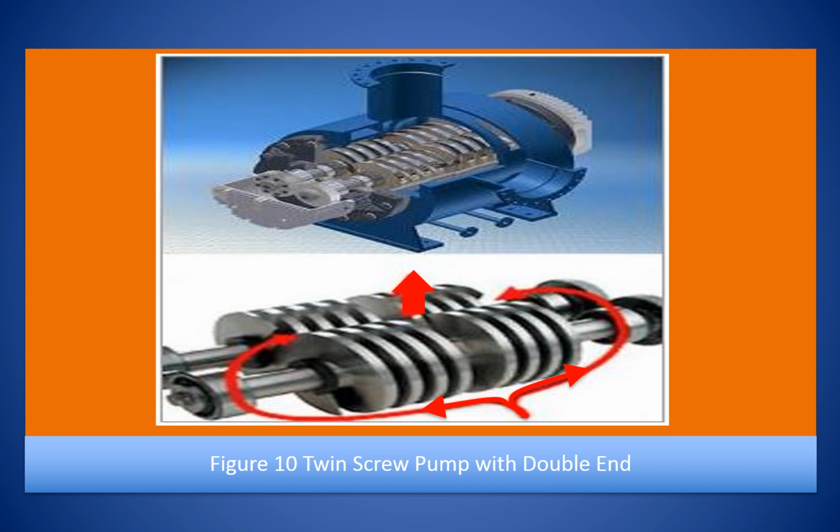The next widely used type of pump under the positive displacement rotary type is the screw pump. These find applications in several industries, in refineries and petrochemicals, particularly for viscous applications. Screw pumps are a more complicated type, featuring 2 or 3 screws with opposing thread. One screw turns clockwise, the other counterclockwise.